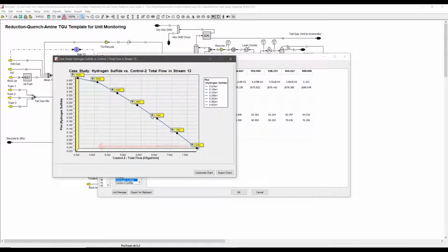We can also see where if we drop the solvent circulation, the TGU recycles less acid gas and is richer in H2S, about 5% rate. Because both of these outcomes open up room in plant capacity, they were considered worthy of trying in operations. The plant dropped rates successfully to 525 GPM without having to trigger a change authorization, which was worth several hundreds of thousands of dollars in sulfur capacity benefits.